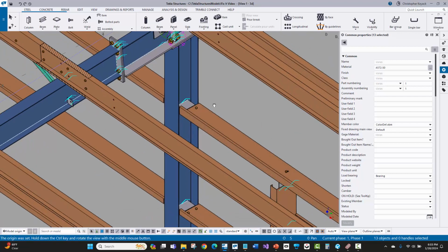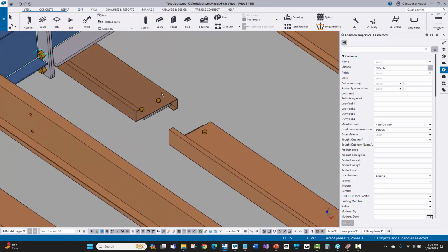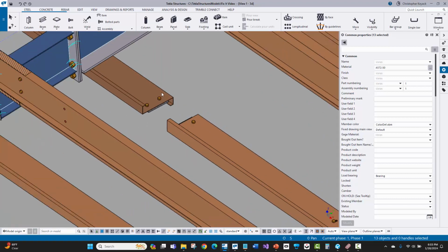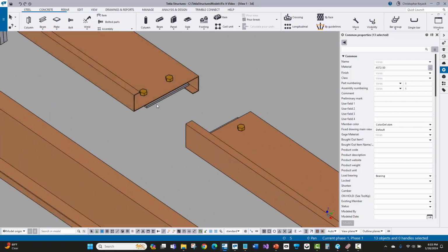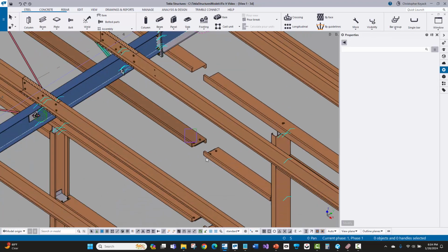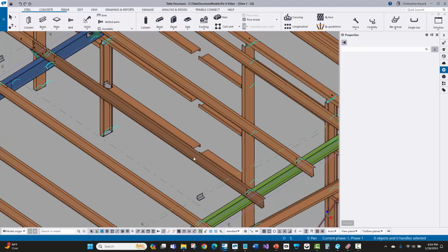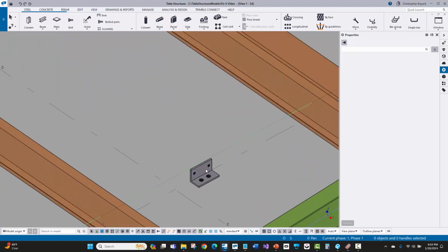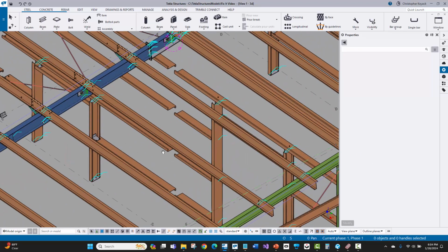Now, in fact, I may undo that real quick because there's something I probably want to delete on all these scenarios before I start doing the copy mirror and the copying of the rest of the columns. I can see here that the residual plates that were there before have not been deleted. So I'm going to just wipe those out, get rid of that. And then I'll make sure that all of these additional clips that we don't need anymore, I'll go to each one of the conditions and delete those out first. And then I'll do the copy of my columns.